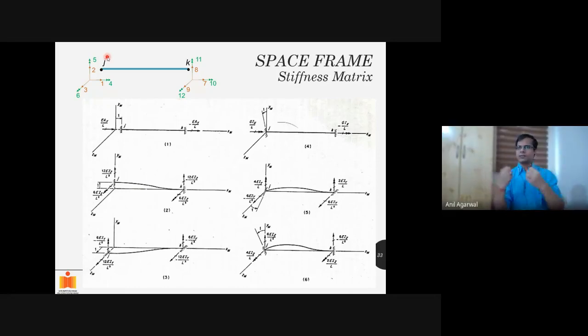So the axial stiffness of the member does not depend on what level of flexural deformation is happening in the flexure. That might be true in the elastic range for most members, as long as we are not accounting for geometric nonlinearities. But it can sometimes be questioned and challenged, and there are limits to how far we can keep making that assumption. For the purpose of this discussion, we are assuming that behavior in the 1st degree of freedom is independent of behavior in the 2, 6 degrees of freedom and the 3, 5 degrees of freedom.